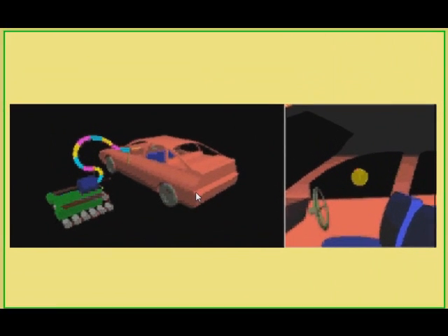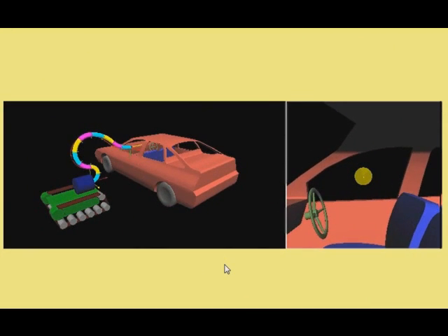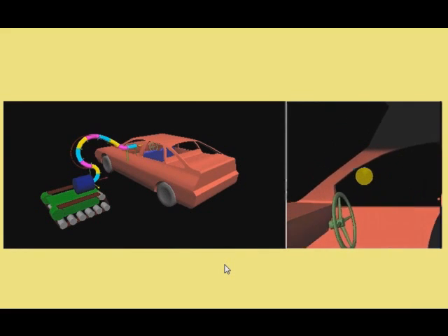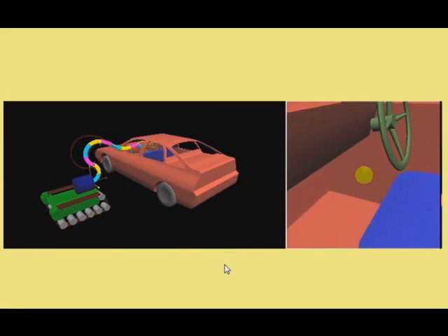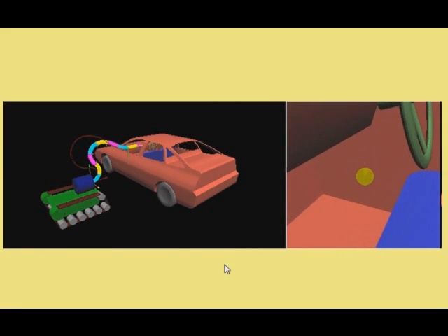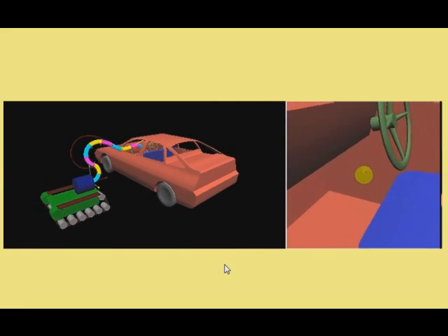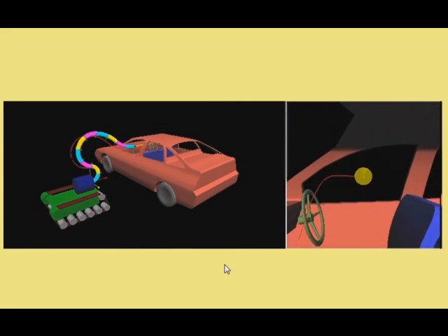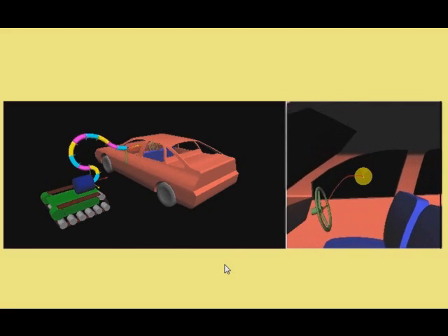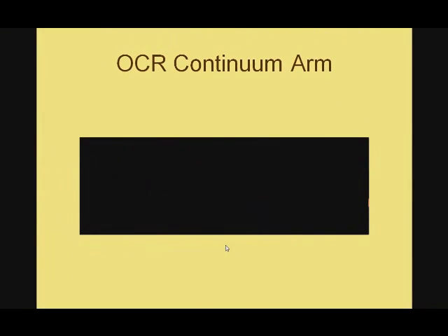If we see the simulation run again, this is a Jacobian-driven simulation, the Jacobian built on top of the Denavit-Hartenberg model for the kinematics. So we can see again the sorts of things that these snake-like robots ought to do. The Jacobian method that we're going to look at in this video is applicable to lots of different scenarios. We will look at it specifically for industrial robot arms, but it's applicable across a much wider range.